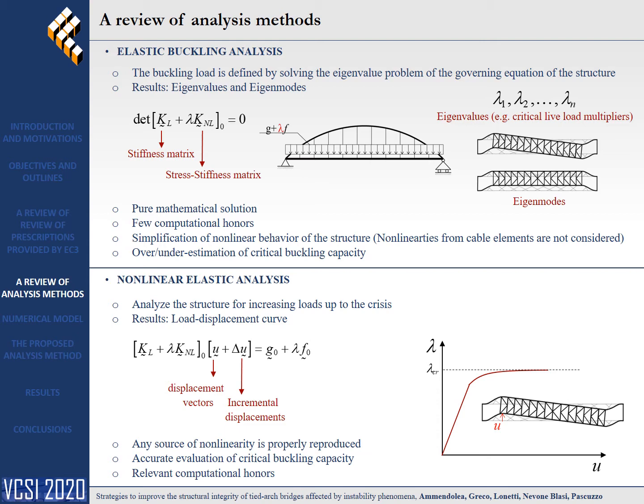However, it involves a considerable simplification of the nonlinear behavior of the structure, thus leading to overestimation of the buckling capacity. On the other hand, nonlinear elastic analysis provides more accurate results, since it considers the path-dependent nature of the applied loads, taking into account the actual deformation involved in the structural system.